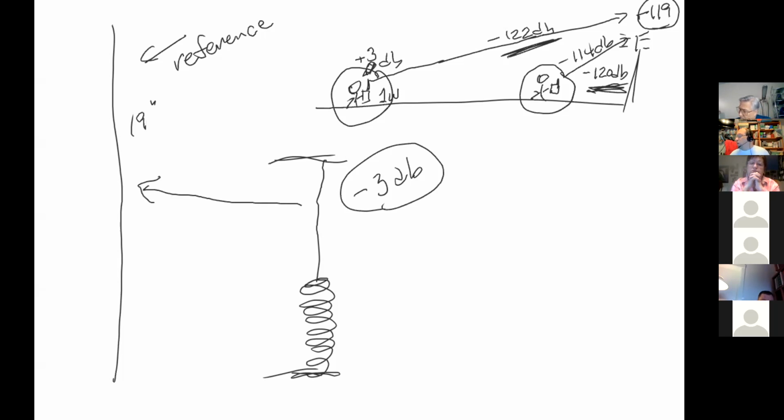So if you're in a place where you have excess gain to spare because of the path loss, you can get away with it. If you're in a place where you don't have gain to spare, you can't. This is actually called antenna loading, and it's very popular because you can make a long antenna very, very short.